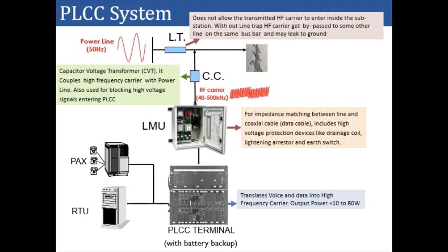Now let us see the architecture of the PLCC system. So here we will see what are the various components we have to send the data as well as voice over the transmission line. The role of the PLCC terminal is to translate voice and data into high frequency carrier. The output which you get from the PLCC terminal is in the range of 10 to 80 watt.